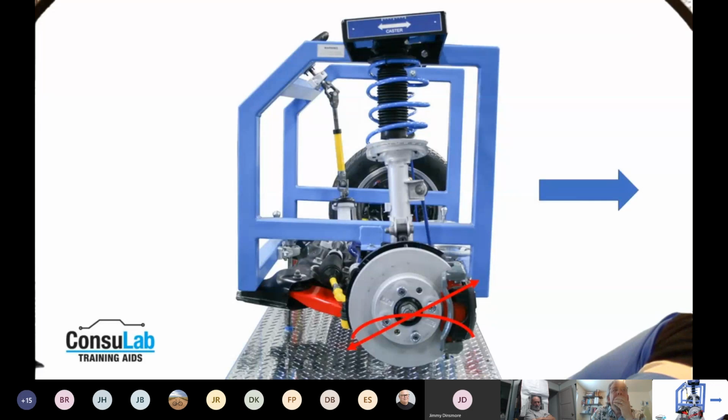And there's a variety of different methodologies too, for how to check the ride height. A lot of the aligners just use a measurement to the fender, but there's a lot of others where you're measuring position of components to the chassis, angle of those components, those types of things. There are measurements from ground to certain points on the body. So yes, ride height is very important.